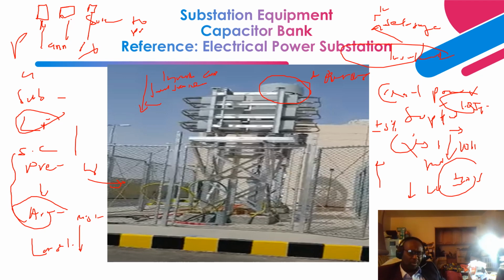If you have a motor that is running, that voltage dip can cause it to stall because the voltage is not adequate for it to be in steady state running condition. So you utilize the air core reactor to limit the inrush current during energization of the capacitor bank, to avoid that transient condition during energization. There are other designs in play.